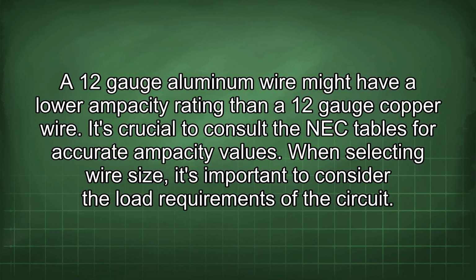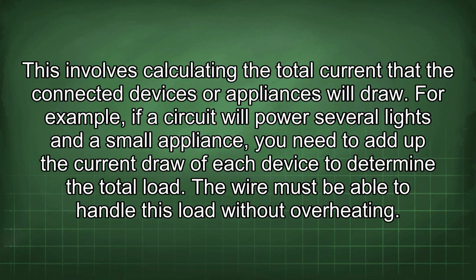When selecting wire size, it's important to consider the load requirements of the circuit. This involves calculating the total current that the connected devices or appliances will draw. For example, if a circuit will power several lights and a small appliance, you need to add up the current draw of each device to determine the total load. The wire must be able to handle this load without overheating.